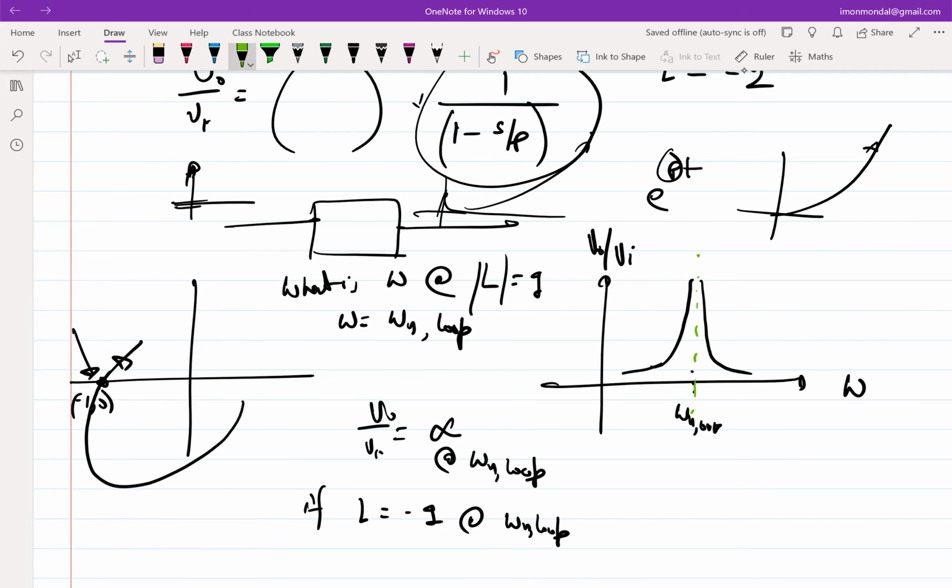Right? We talked about these infinite gains many times before, when we were discussing Y parameters, and sometime later also. So this is what I wanted to mean at that time, that infinite gain means instability. Okay, so this essentially means that you are going to have sinusoidal oscillations at a frequency of omega U loop, because this is the transfer function of an oscillator.